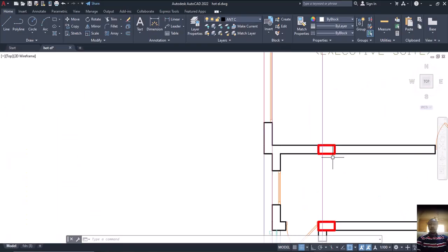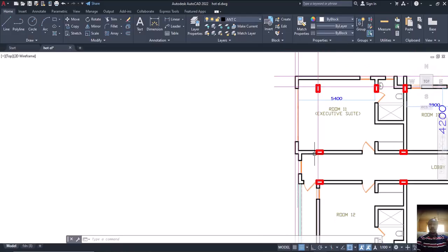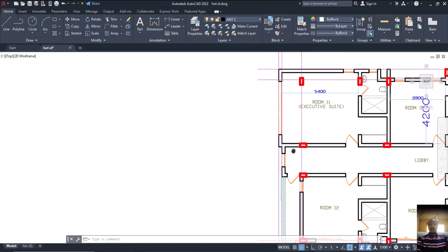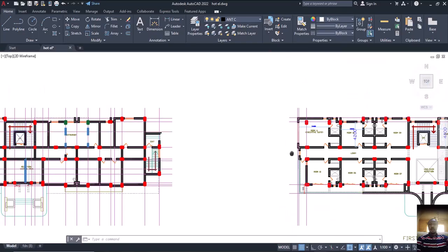But since it does not interfere with anything, are you hearing me? It does not interfere with anything, and if I shift it from here to this place, it makes this one go very long. Not that it will not pass, it will pass, but it will require a big beam depth, isn't it? So on that note, I want this column to still flush to go.